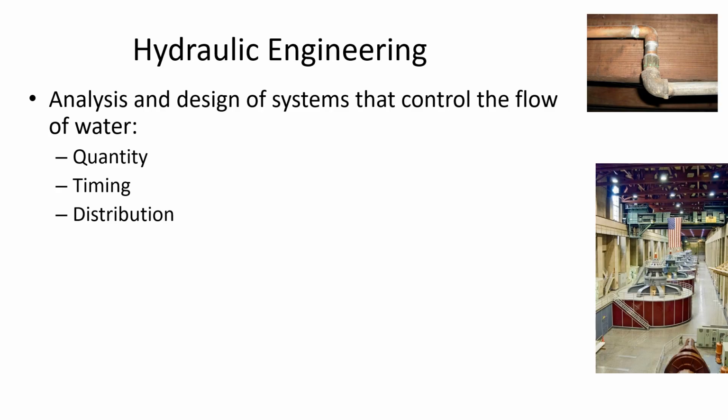This course includes both open channel flow, which is what we've just been looking at. We've been looking at the water bridge and the water wheel. That's considered open channel flow, but it also has closed conduit flow. So there's both water flowing through pipes and water that's going through open channels that's not pressurized. And there's very different equations and very different design methods we have to use for those two different situations.